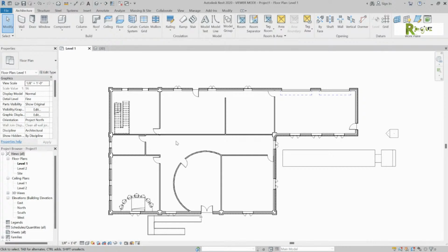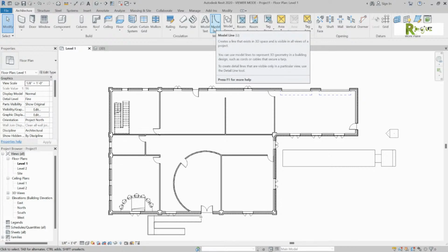Do you see that next group is going to be model text, model lines, and model groups. If you draw model lines, Brian's going to punch you. Don't draw model lines. Just don't use the model text button. Just don't even do it. You're going to find that that's what we delete. If we draw lines, they're under annotate and they're called detail lines. Do not draw model lines.